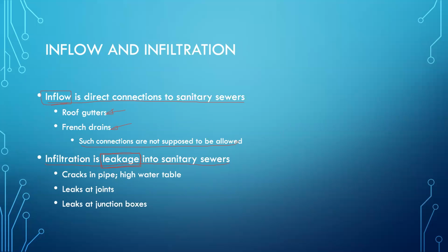It's not like the people that make the connections are out and out criminals. But they take flow from a roof gutter, and rather than run it across their yard, in some cases, it seems hydraulically easy, just connect it into the sanitary system. But that's technically illegal, and code enforcement could issue a citation if the owner is unwilling to break that connection.